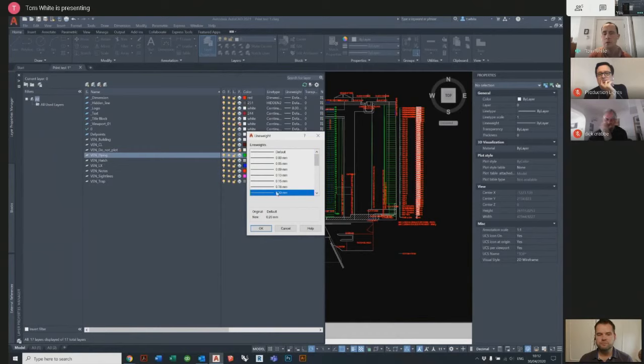Often I'm producing 3D drawings at this stage, and to produce an A3 drawing, which is a technical representation of what the designer chooses to design, I use 0.2 of a millimeter, because it's kind of a middle ground. It's not too thick that you don't really know where you're going, and it's not too thin that when you produce an A4 drawing, when you print it at home, in comparison to an A3 where it's meant to be set up, it's kind of a middle ground. Dom, do you have a sort of similar rule of thumb or anything, or something that you tend to use?